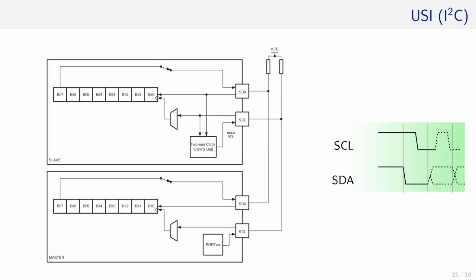A bit more complex is I2C. For one, the pin for data out and data in is the same. Again, the clock is controlled in software. First, a start condition needs to be created.